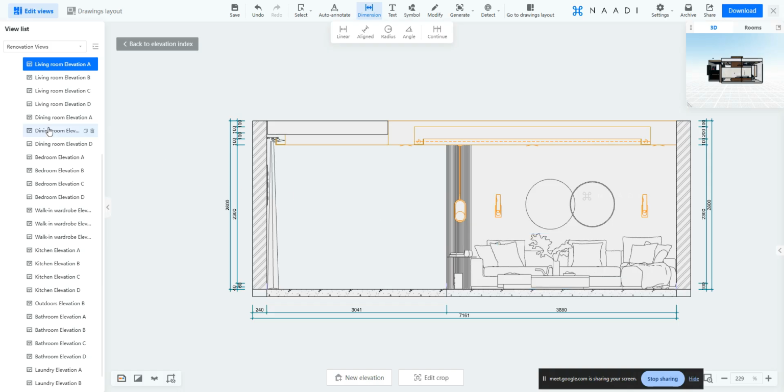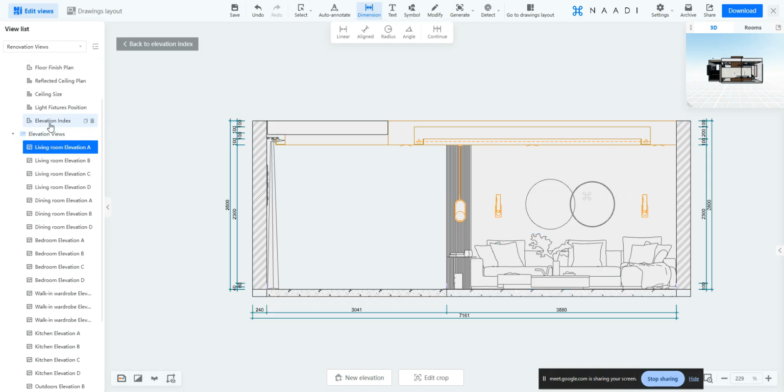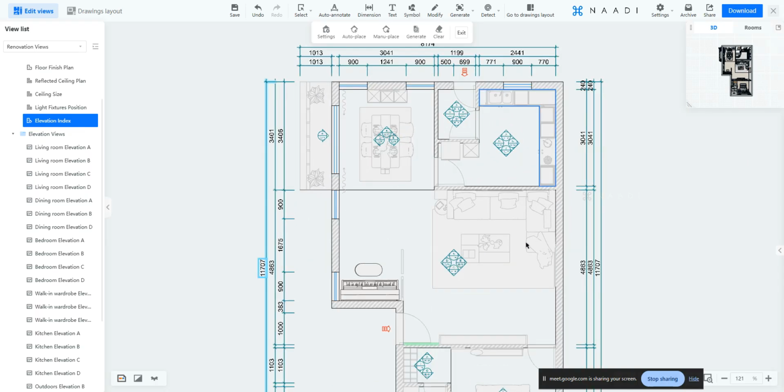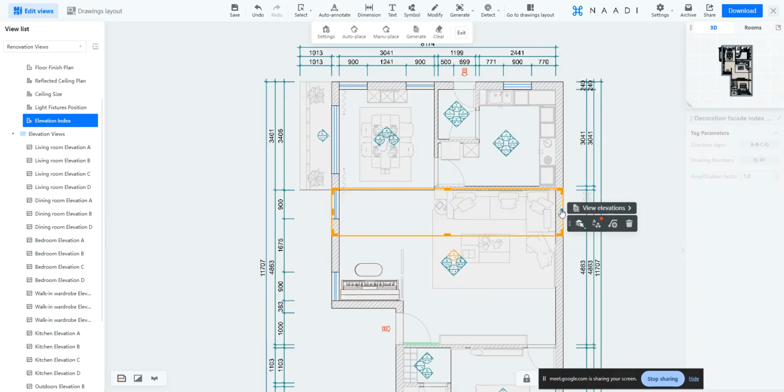In those cases, go to the same elevation tag, and in this extend boundary, this right and left we are able to adjust, right? This represents the horizontal extent for which you would like to generate the elevation. Apart from this, can you see this extent, the farthest extent from your elevation tag, this one? This will control how long or how distant you want your elevation to be.